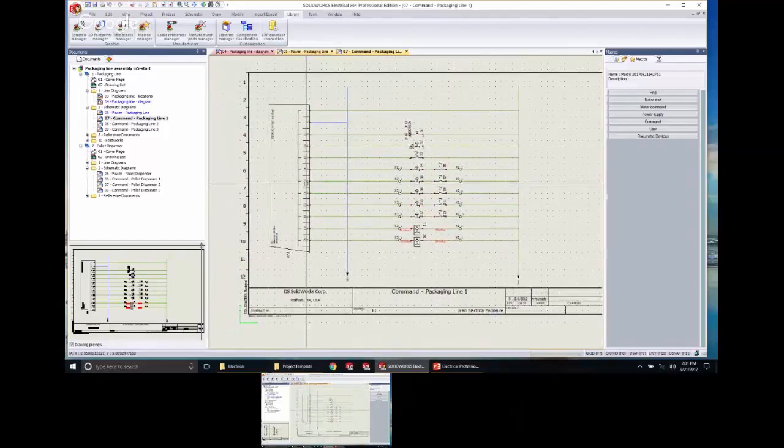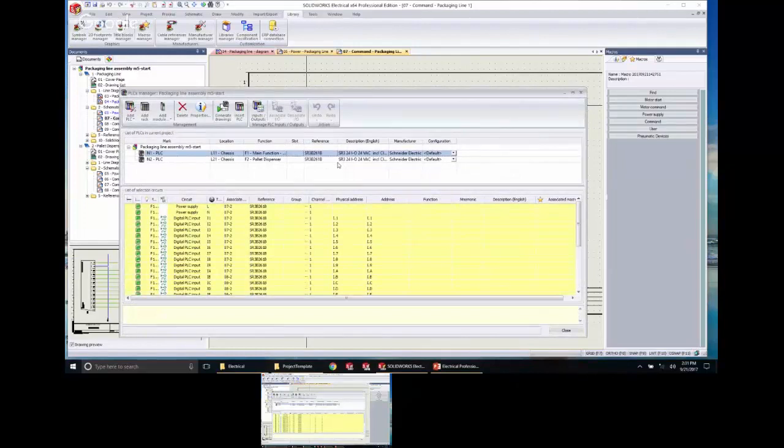You guys using PLCs at all? Yeah. It's a nice PLC manager. Again, just like the PCBs, it's not for designing them, but it is for representing them. So let's go in and look at this PLC. So you can see the manufacturer. Again, PLCs need that manufacturer. So you get that data about the circuits, the inputs, the outputs, the mnemonics, descriptions about what's going on. You can go in here, multiple PLCs. You can also do racks, right, with cards. So that's this add rack, add module. So there's quite a bit you can do with PLCs.